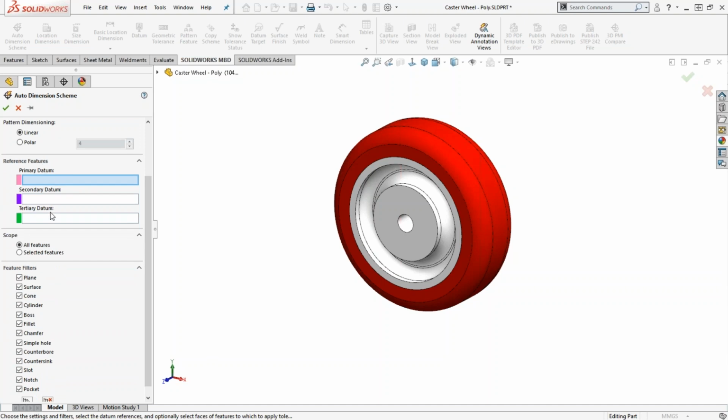Here are your datum references. The datums are the points of reference for all the measurements in 3D space. So the datums are what define your model's position or the reference points for measurements in 3D space. In this case, we only need to do two because it's kind of a rotated part, so it's symmetric in two different axes or two different planes there. So we only need to define a primary datum and a secondary datum for this one. Tertiary datum will just be over definition in this case. So we'll start with the primary datum.